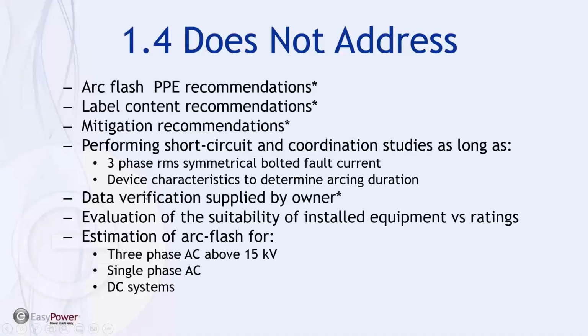There's also a lack of explanation for data verification as supplied by the owner. And I think this gets to the heart of most of what I see as the focus of this new model, or this new standard. It does not evaluate the suitability of any installed equipment versus ratings. Normally we refer to this as equipment duty. And there's no mention or discussion of 3-phase arc flash above 15,000 volts, single-phase arc flash, and anything in DC systems. All of that was a little bit of a surprise to me coming off the first part of the exposure.